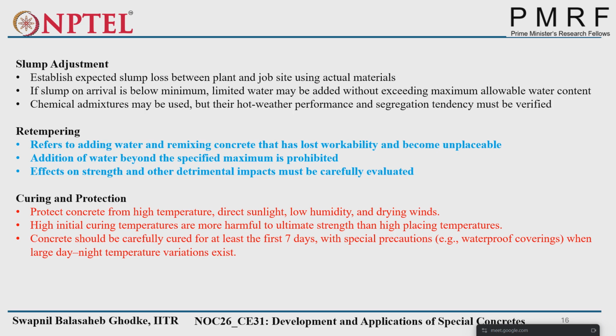So ultimately, not all the cement will hydrate. Some will remain unhydrated. Strength will not be achieved as required, and durability will also be affected. So what it says is that concrete should be carefully cured for at least the first 7 days, with special precautions like waterproof coverings when large day-night temperature variations exist.